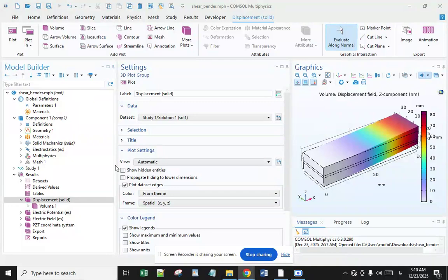The convergence of the element to the reference tip's displacement is shown in this simulation for the shear actuation mechanism. For the extension actuation mechanism, the finite element produced errors of less than 0.05 percent for the beam's deflection. It is clear that the present element is very precise even with a low number of elements, less than 2% for two elements. Besides, it converges monotonically and rapidly to the desired tip's deflection.